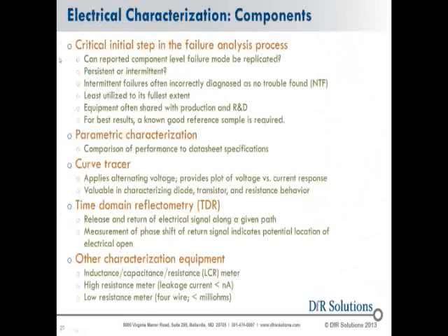Okay, so electrical characterization again of components. Sometimes you're working with a complete module or circuit board assembly, and you've got to hunt down what it is, and then eventually you get down to this IC or this resistor or this part acting up. And if you verify that it is not an issue with the way the part is attached or wired in or connected to the rest of the system, then you usually will detach the part from the circuit board or take it out of the system and start running specific evaluations of electrical performance on whatever that device is.